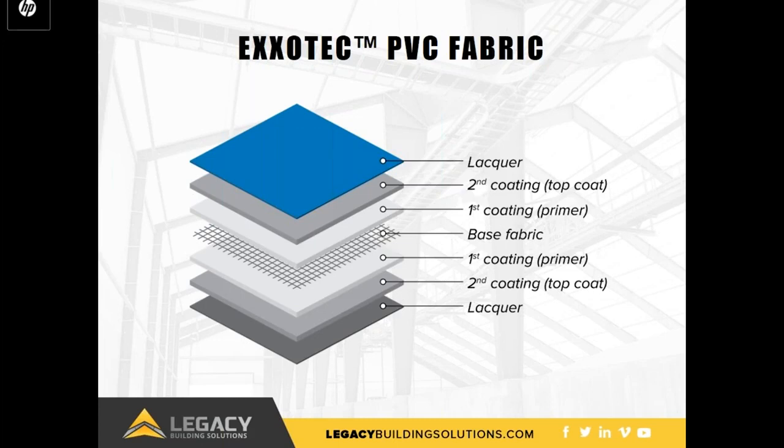The final layer of the fabric is a lacquer. The clear lacquer has 2 primary roles: to keep plasticizers within the PVC from coming out, and to provide a smooth, self-cleaning finish. Many PVC fabrics are also flame retardant in accordance to NFPA 701 and the California Fire Marshals. The picture shows Exotech, which is a PVC fabric exclusive to Legacy.